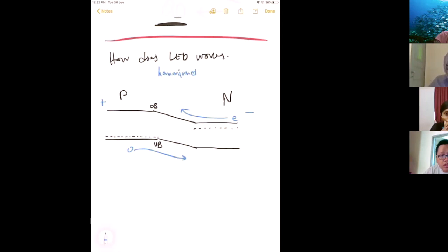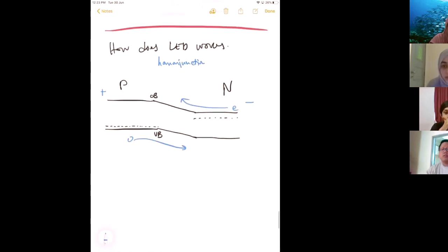Maybe if I want some fun, I'll put in an exam question with a heterojunction. So you need to read the question carefully. The P is made of what? Or I say P and N are the same material, and I is another material. So you need to draw accordingly. Electrons will diffuse from N to P, holes will diffuse. So the word is diffusion. Make sure you use the right word.